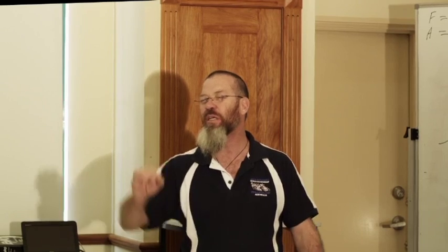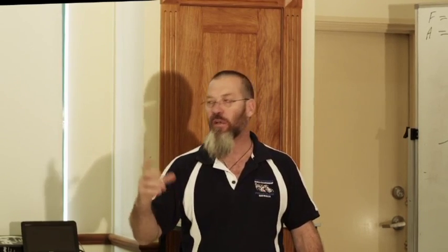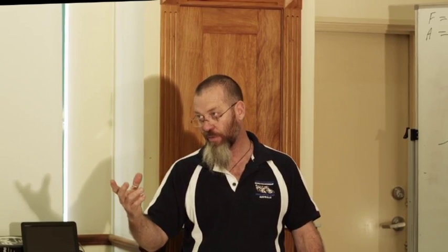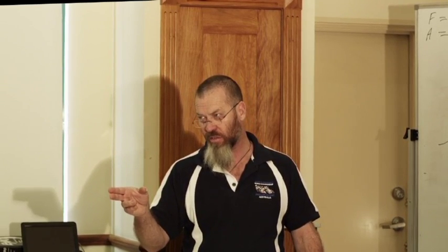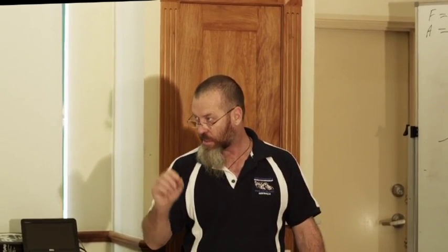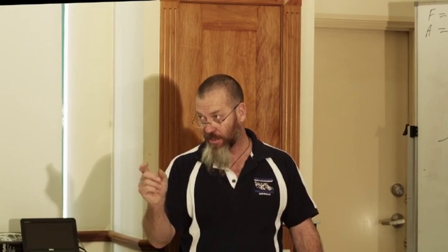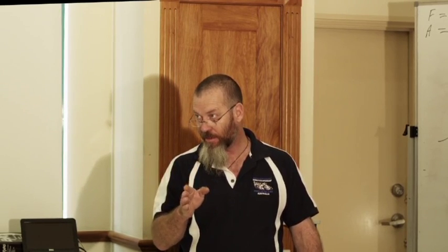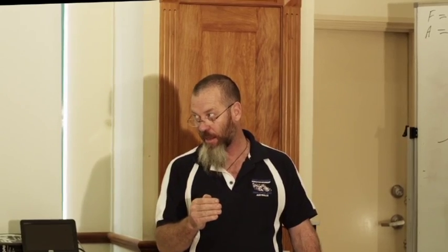So in fact, that hole for that Dynabolt should be 70 mil, and the hole for an M10, M12 is 16 mil, is it not? Is it 16 or 14? 14. So it's 70 plus 7 to get to the centre of the hole. That's 77 mil in from the edge of the slab.